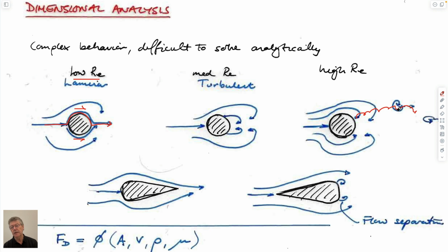And indeed, just like Tacoma Narrows, you get a vortex shed from the top of the sphere, and then alternately one shed from the bottom. So if you look downstream, to take a picture in time, you'd see a continuing upper, lower, upper, lower, upper, lower traveling vortices going downstream.